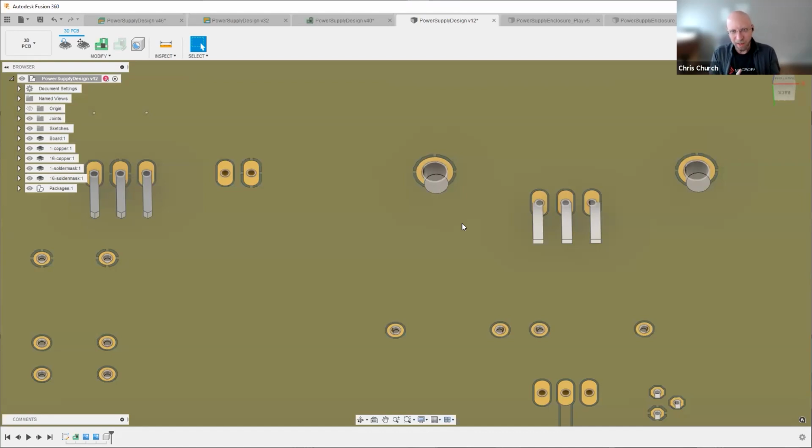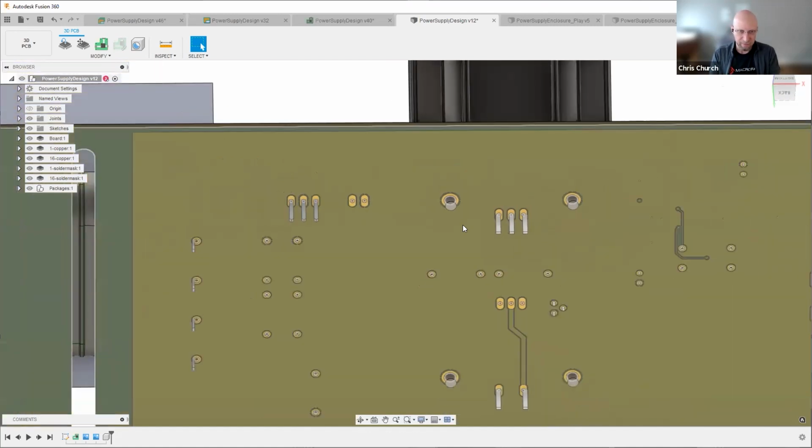So while it is perfectly possible for us to solder those, it does create some challenges in the amount of heat we have to apply to get those up to the temperature they're going to need to be. And this is the sort of expertise when you've done a few of these, a few thousand of these, right? You start to see these kinds of patterns. So, what we see as a more successful strategy is we can apply solder there for additional support.